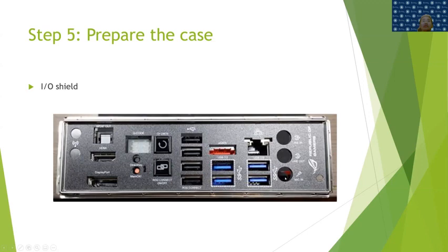Now generally the I/O shield will be like a slot that you just push in, and you're going to make sure that the I/O shield is really flush around all the edges, which is important. Otherwise, it's not going to be fully secured.